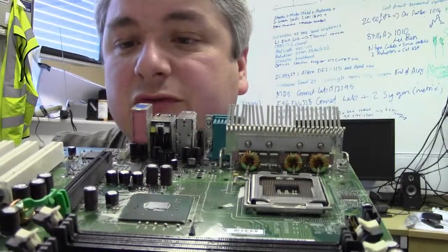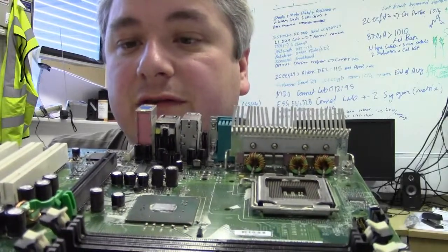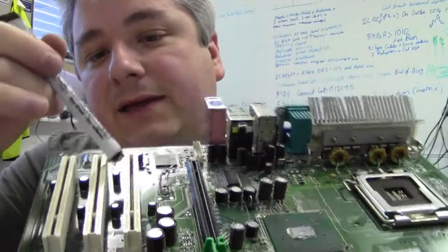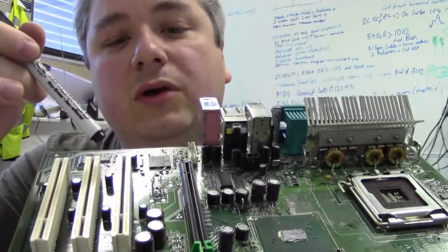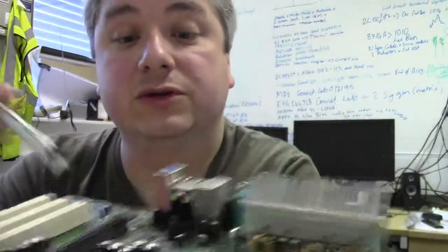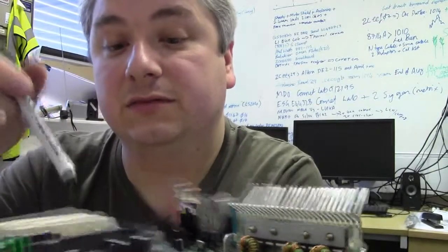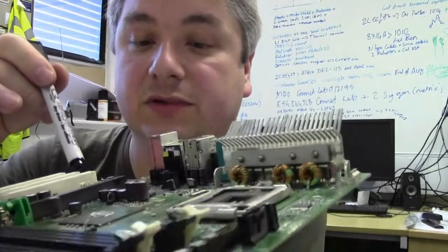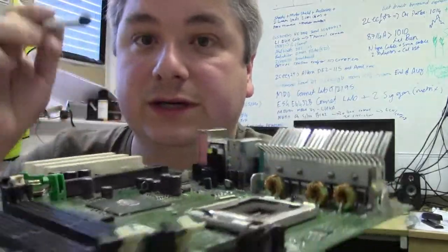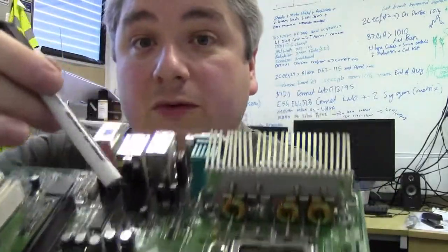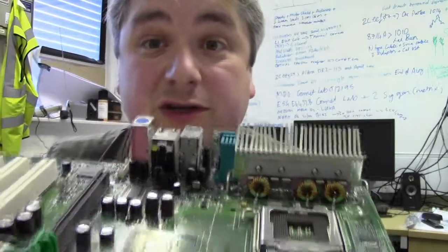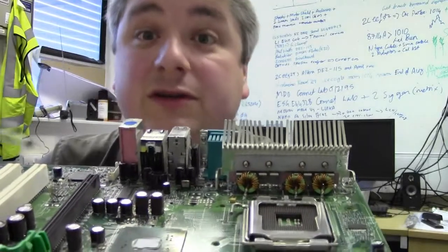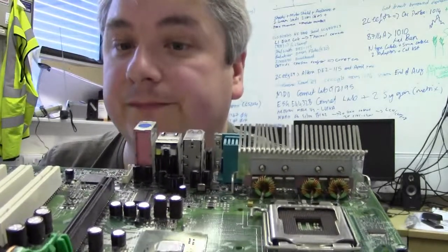Like these ones are all 1500s. The ones that are in between here, these are all 1 micros. The ones over here, you've got some 470s and some 220s, and they're all the same sort of dimensions, the same sort of size, so you can get an idea of what the values are by observing the components that are surrounding those ones that have gone.